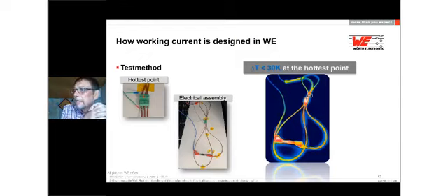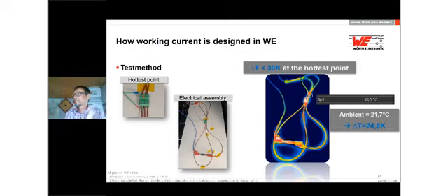And this is what happened. We made a picture with a thermal camera, and we measured the hottest point. It's the point SP1, as you can see here in the middle of our connector. And remember, the delta T must be under 30 Kelvin. So let's check what happened. We had an ambient room temperature of 21.7 degrees Celsius. And then we put 20 amps on this connector, and the delta is 24.8 Kelvin. That means the end temperature was 46.5 Celsius, minus the ambient temperature gives us the delta, and the delta in this case is 24.8 K.